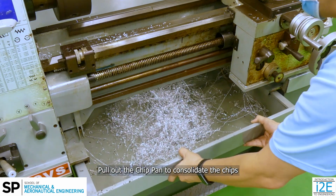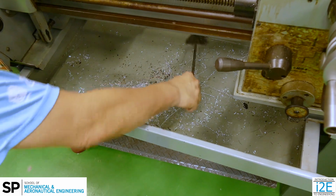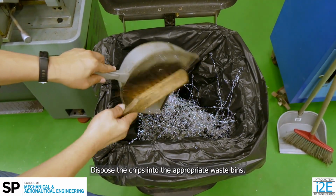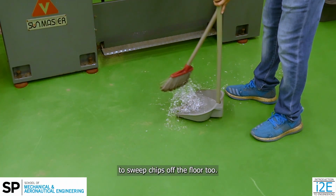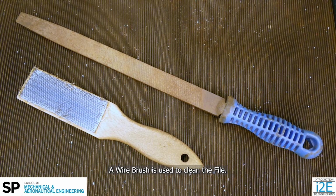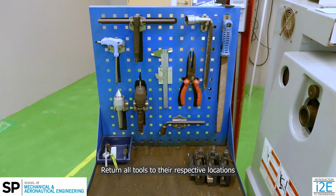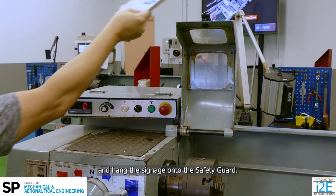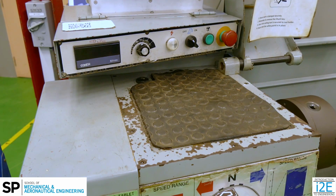Pull out the chip pan to consolidate the chips and brush out the chips onto a dustpan. Dispose of the chips into the appropriate waste bins. Use a broom and a dustpan to sweep chips off the floor too. Clean the tools before storing them. A wire brush is used to clean the file. Return all tools to their respective locations and hang the signage onto the safety guard. Finally, power off the machine.